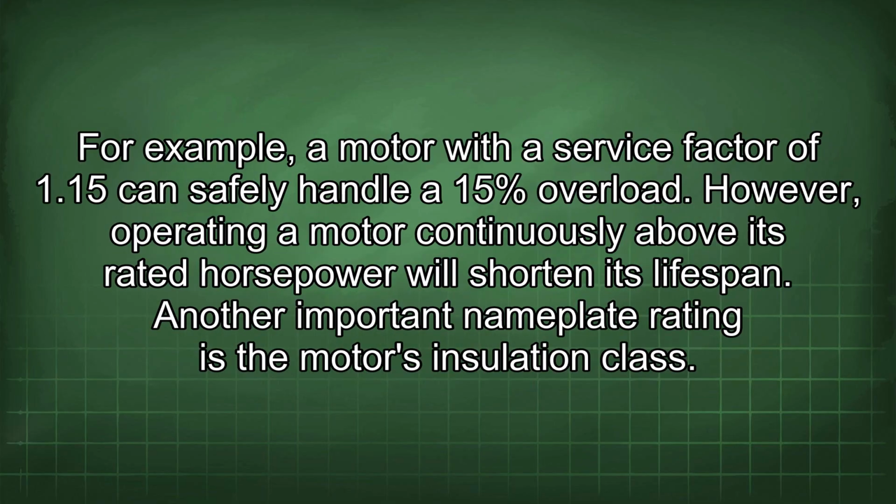For example, a motor with a service factor of 1.15 can safely handle a 15% overload. However, operating a motor continuously above its rated horsepower will shorten its lifespan.